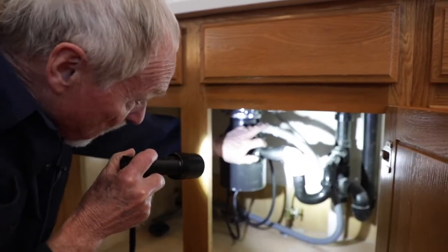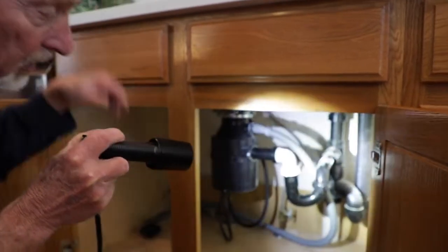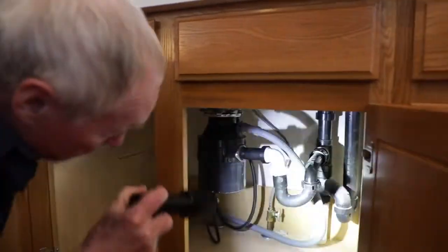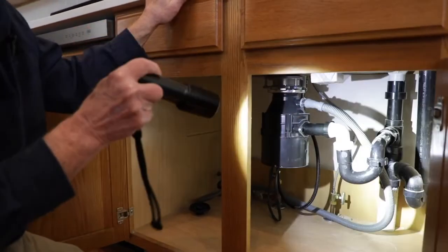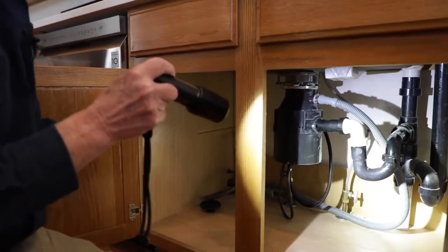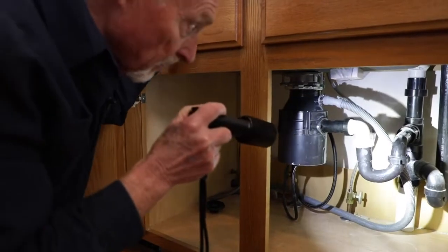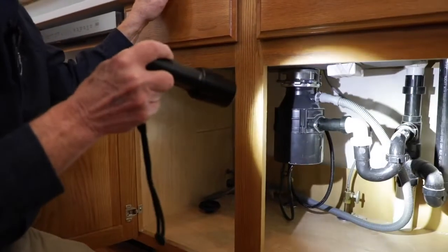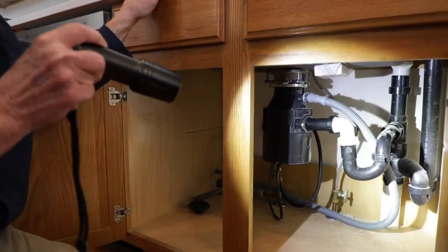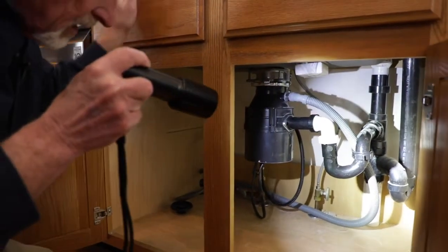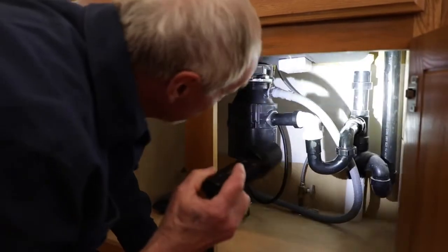With the discharge going into the discharge vent here, as it should be done, that would keep the P-trap full of water and prevent sewer gases from backing into the house. So sometimes it takes a little essay to explain this stuff in our reports, and I see an essay in the future here.